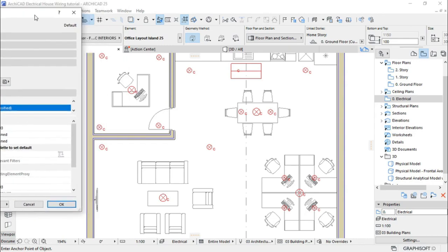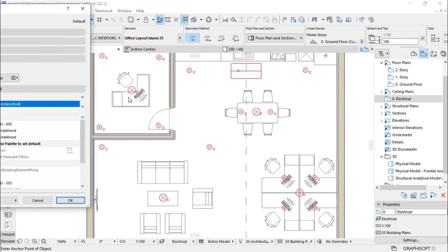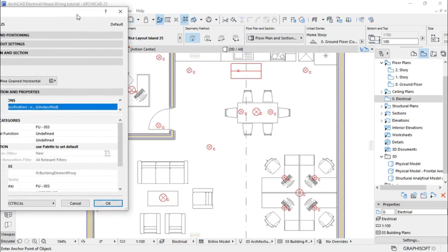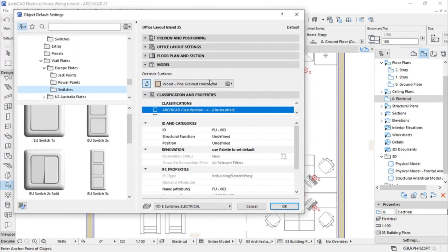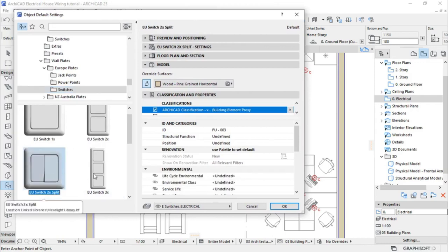It's going to be a switch that will control both the general light and the downlight. So I'll give an option to switch on the downlights only, or the general light separately. So I would have to have two switches like this one.